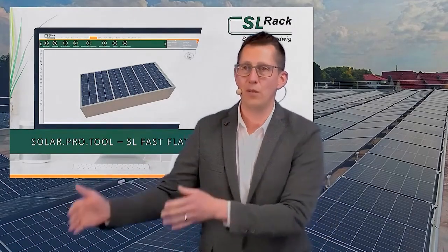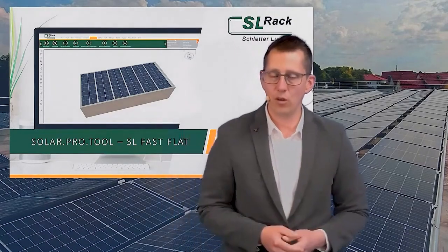And now, having entered the ground pressure of 40 kN, we are automatically calculating the number of ground shoes. Now, it's really important that you keep in mind at which location I am. The snow also increases the pressure on the entire structure and has an impact on the load-bearing capacity of the substructure. That means if I'm with hard rock, or whatever it's called, in, for example, Düsseldorf, I can build without any issues. Maybe in Rosenheim, it might be problematic again because I'm getting too heavy loads here. I just want to pass that on to you.